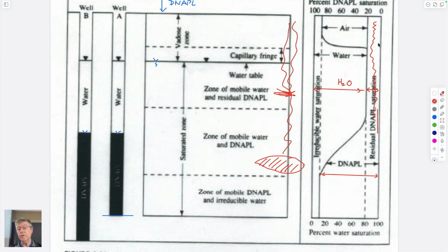And it's predicated on what the capillary pressure versus saturation curve would look like if we convert a capillary pressure into an elevation. And actually it's not that. It has to be pre-multiplied by G, right? This is a unit weight, it has to be a unit weight. Units of stress and units of stress. So you might want to correct that earlier in our notes.